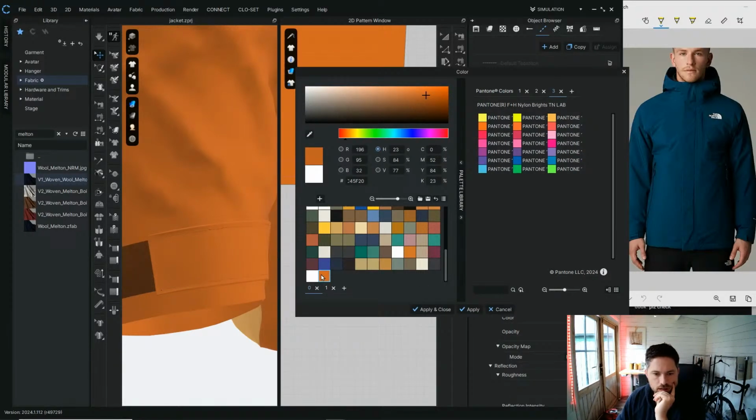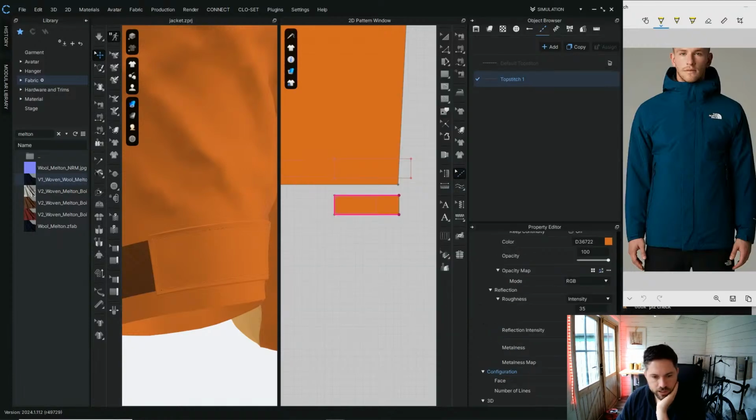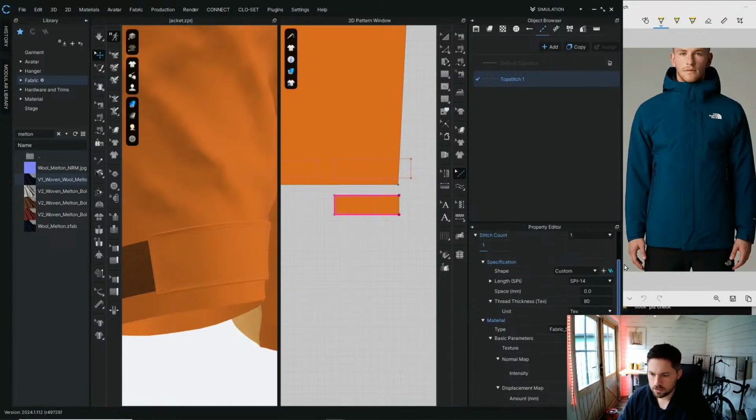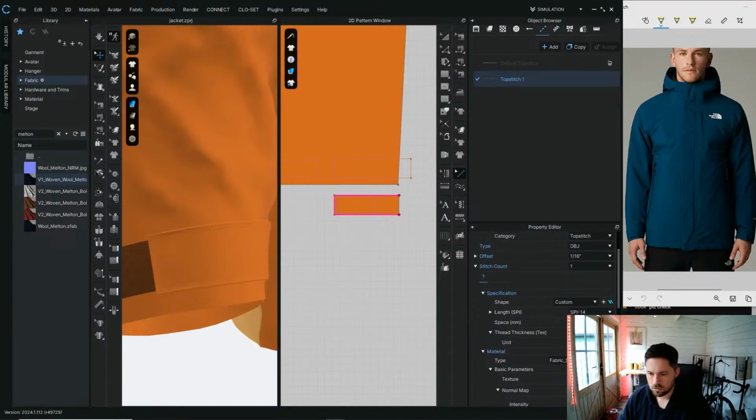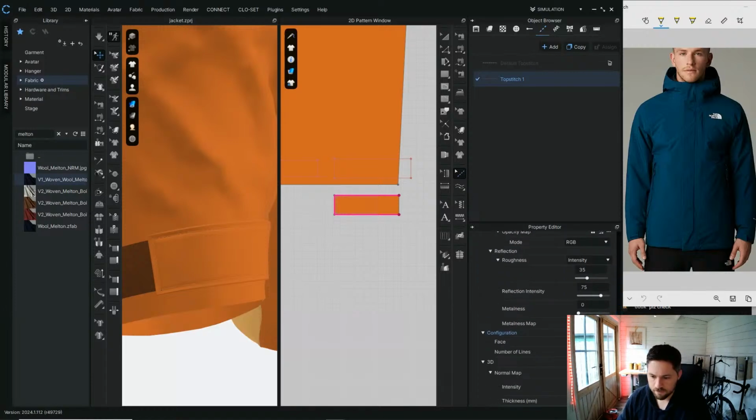Actually, no. Keep it the same, because what I'm going to do is add a 3D line to it. You might have come across this problem. I talk about this every single time. As soon as you click the 3D, it doesn't show on here. What you need to do is go to the thickness, click up and down, basically, and it gives it your thickness.